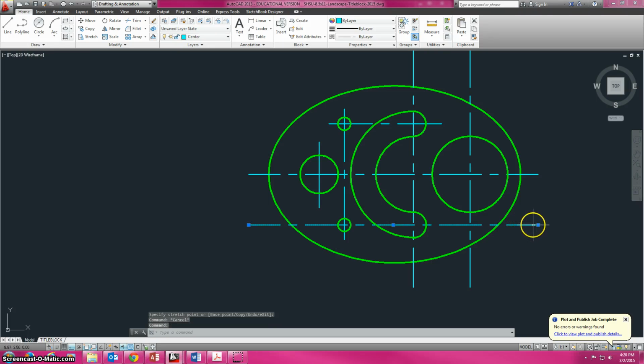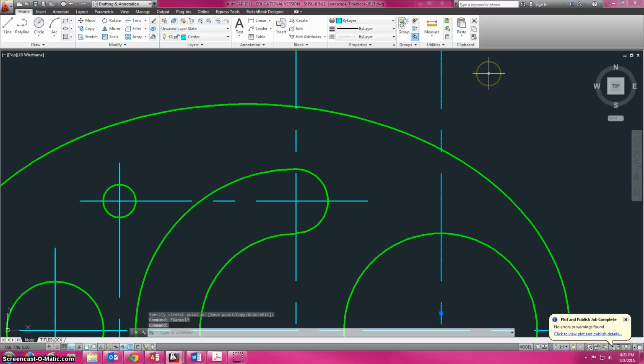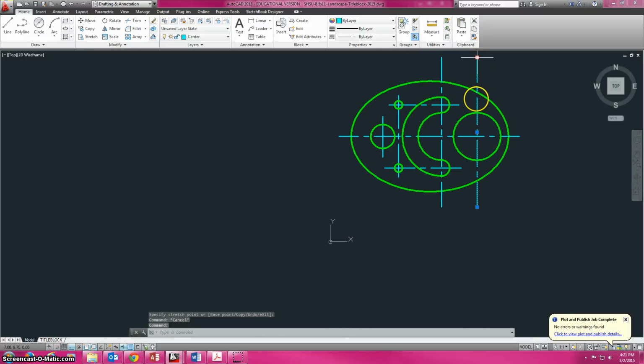And that would be why some students like to draw the lines and then just trim, because then they can make sure that they're drawing lined up perfectly. But we can change a line type scale if we're concerned about a specific line type that we're using and we're afraid that it's not showing and demonstrating itself and it's not coming out right on the drawing. So if we've got some concerns for that, if we're looking at it and we realize that it looks off, it's not right, we can fix that.